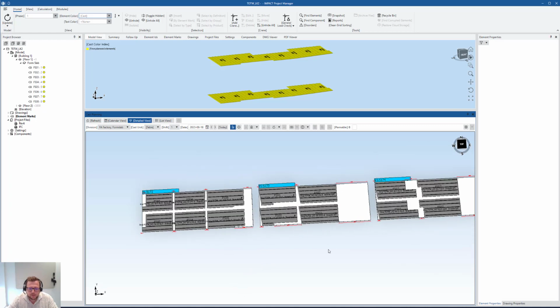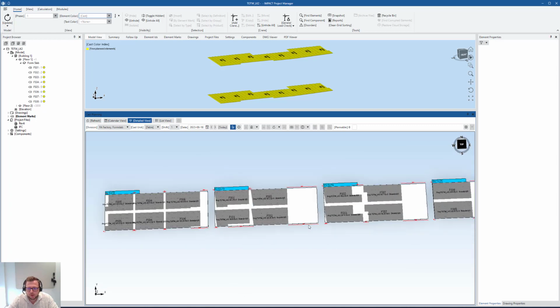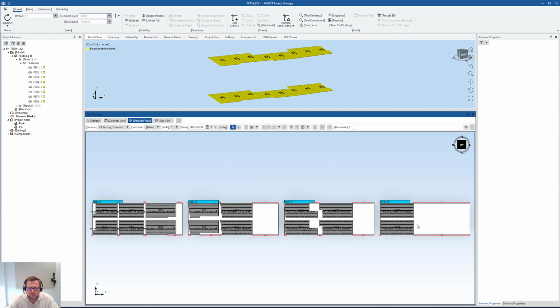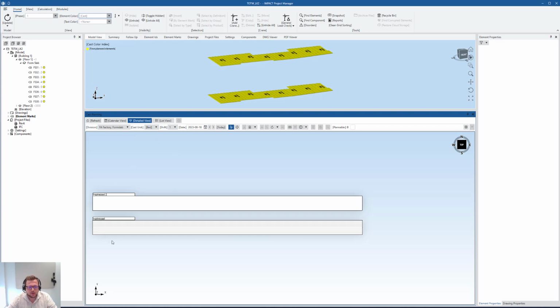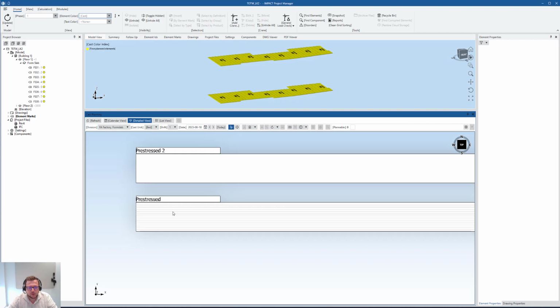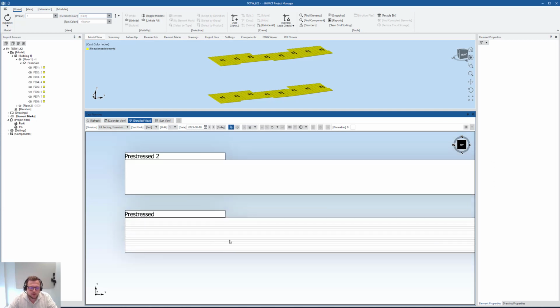And this is for normal non-pre-stressed form slabs. If you would cast pre-stressed form slabs, you can do that as well, but then you use another method. So I don't have any pre-stressed ones, but I have prepared 2 options here. So you create beds in your standard. Either you have one that has restrictions on the placement of the strands, like we have here.